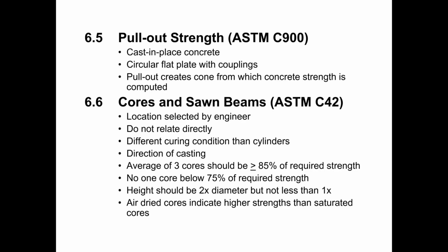The moisture condition of the core will affect the indicated strength. Previous versions of ASTM C42 did not really get into specifying how the cores should be stored prior to testing. But more recent versions of ASTM C42 do dictate storage requirements in recognition that the moisture content of the core does affect the strength.